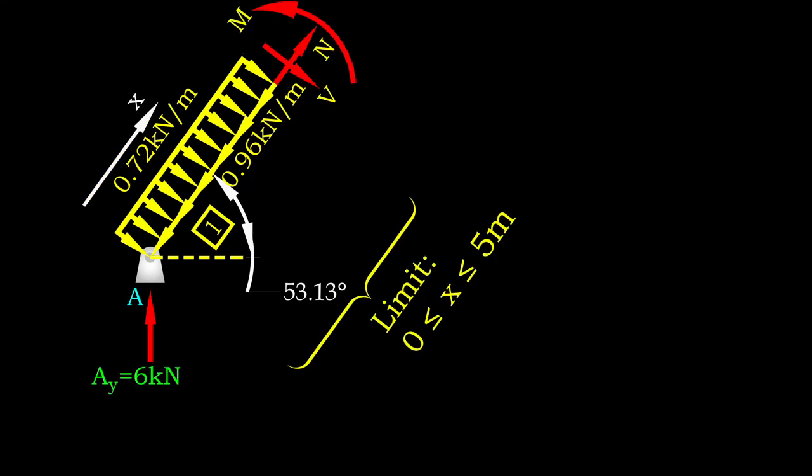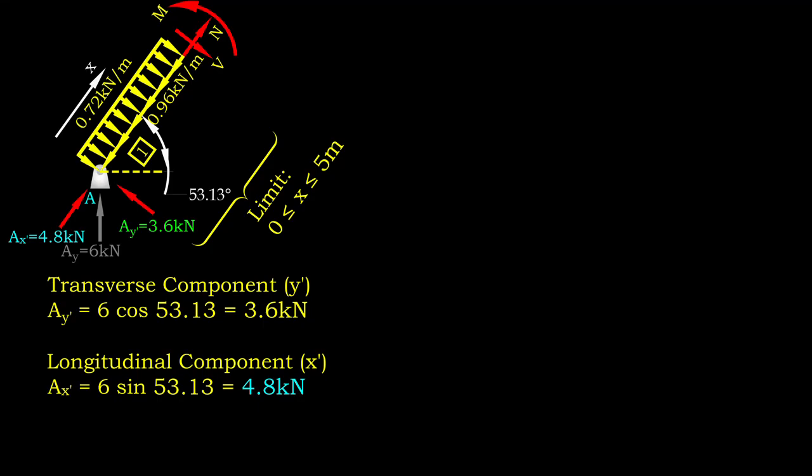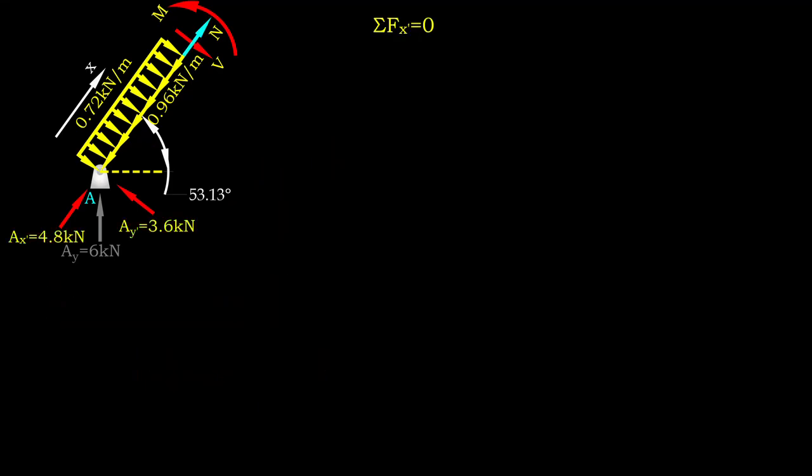Let's check out the first segment. We need to resolve the reaction forces into transverse and longitudinal components like what we did for the snow load. After that, we can proceed with cutting section and determine the internal force functions.